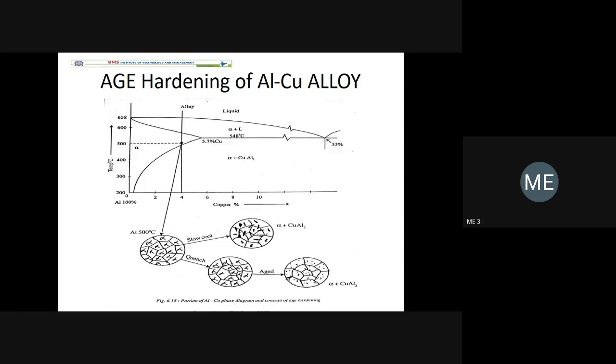Next week you come on the same day, same time, after 1 week. The remaining 5 samples are tested, and he expected one result but got an unexpected result. Instead of hardness 50, and I'm just giving an example to understand the concept, not exact numbers, all specimens having the same composition and process, he got a hardness number of around 70 for the remaining 5 specimens. So what might be the reason? Imagine everything is correct: all procedures followed, all hardness testing machines. What might be the reason?